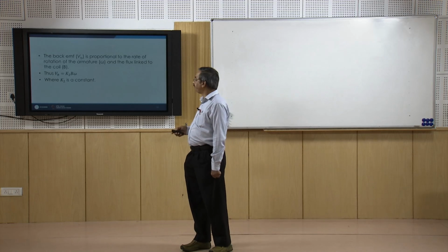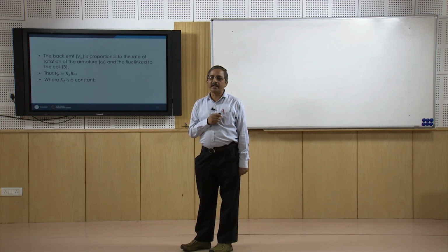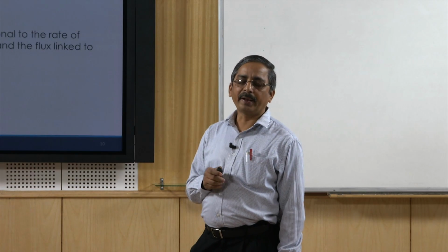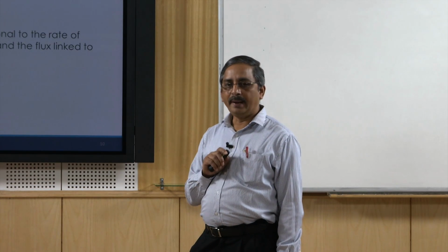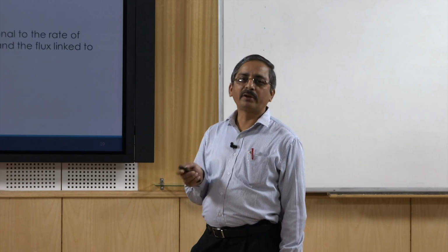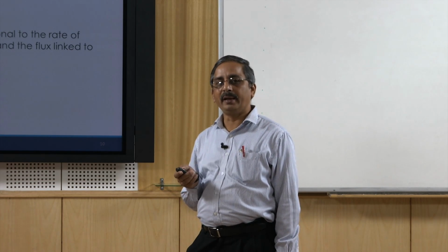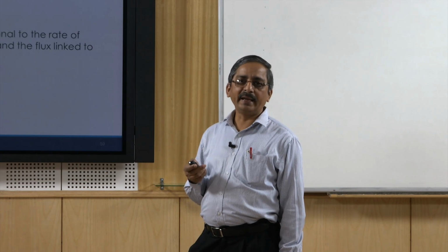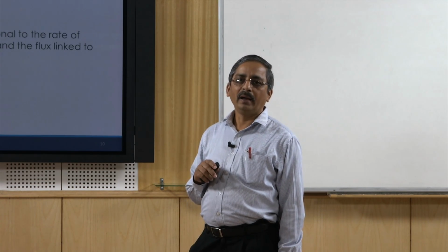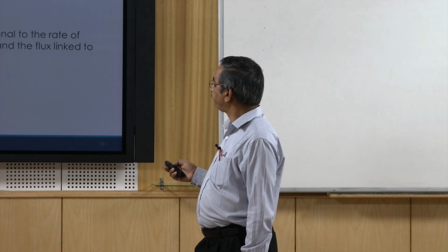Now, as I said, your torque is going to be a function of B and I A. So based on what you are going to change, you can have the torque. You can get the torque both ways: by keeping I A constant and varying B, or by varying I A and keeping B constant.